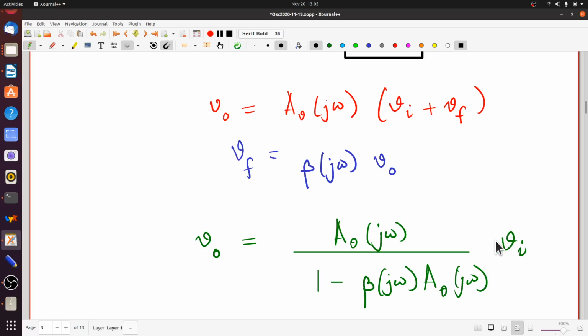So this is again very similar to a result we had for negative feedback before. The only difference is that there we had a plus sign here, and because of negative feedback, the gain went down. Here, on the other hand, the gain of the amplifier goes up. That's easily understandable: the output is feeding back and helping the input, so the output should be larger.